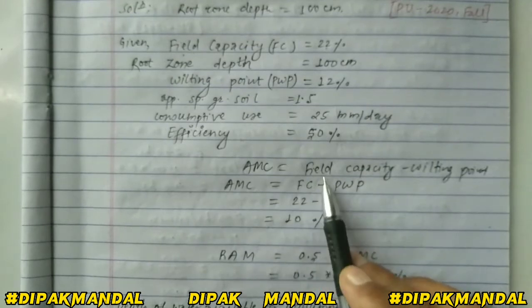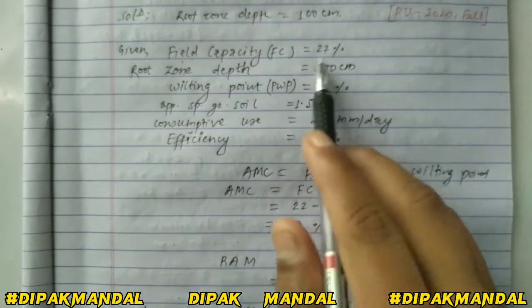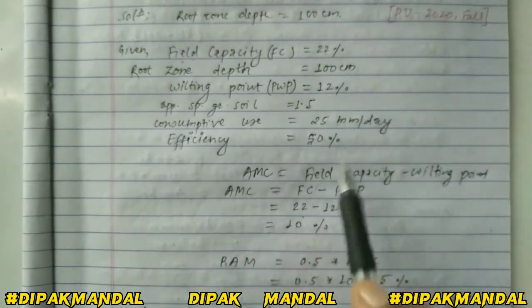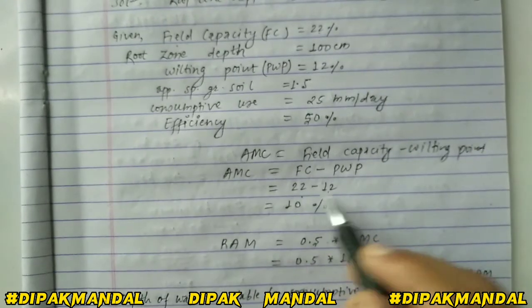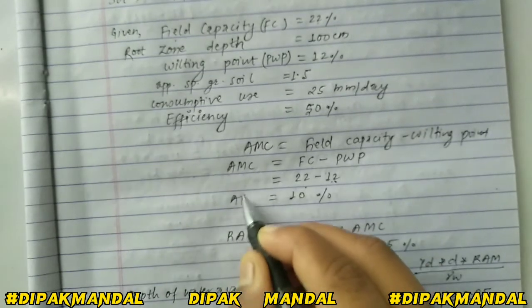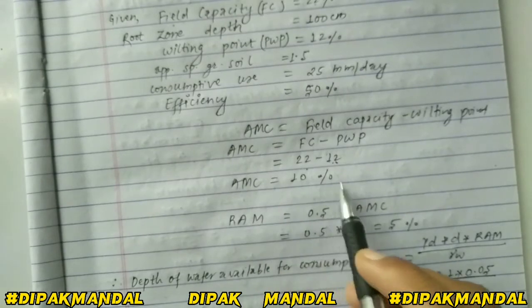So we have been given field capacity equal to 22%. So we just keep the value 22 minus the wilting point. The wilting point value is 12%. So we subtract this value, and the value of AMC becomes 10%. Okay, so we have calculated the value of AMC, that is 10%.